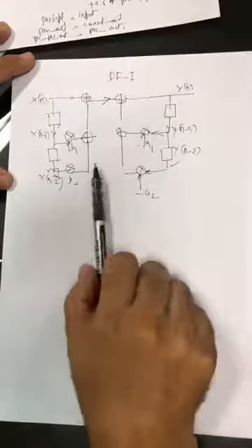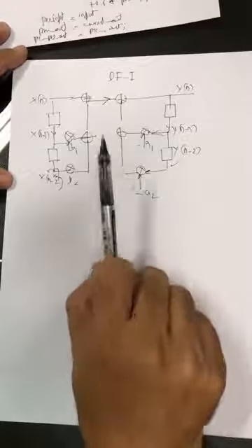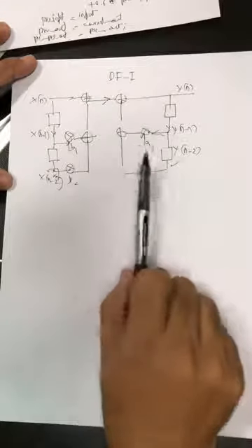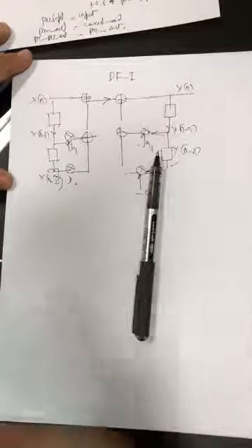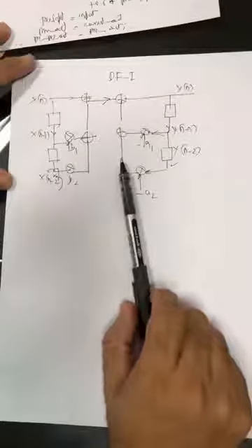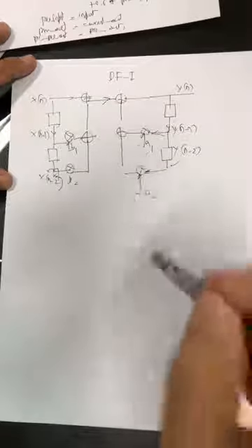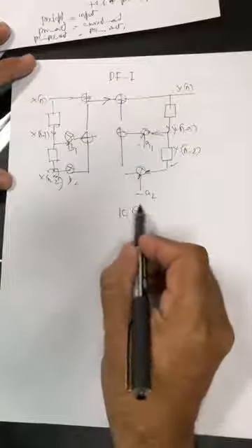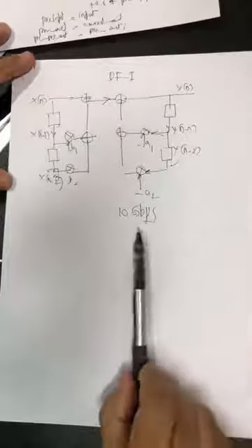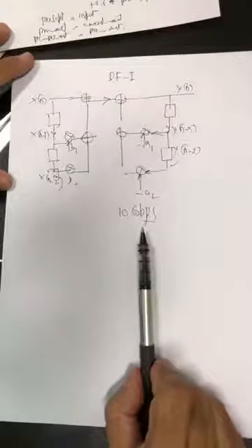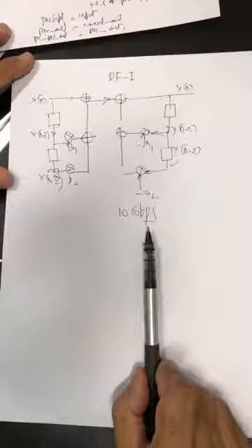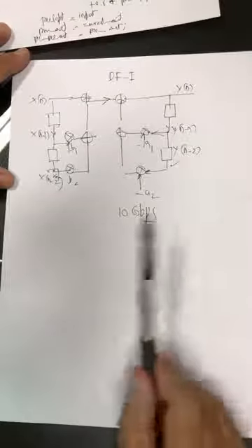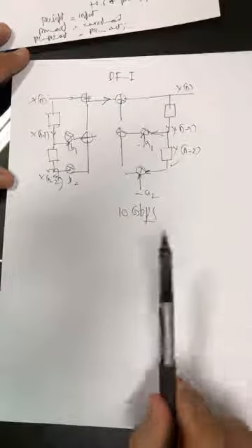They're doing the PhDs, because this is all signal processing is doing, it's just implementing FIR filters, IIR filters, but their length and a very, very high speed, because if it is a 5G modem, the 5G modem has to give you 10 gigabit per second. So just imagine 10 gigabit per second, okay? So all the filtering must be happening, the data which you have to process must be at an even higher rate, and you are passing it through filters at this rate.